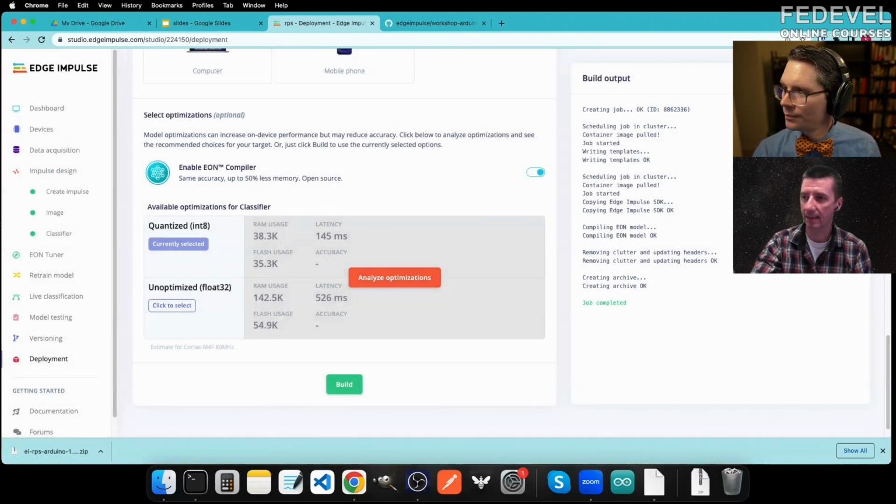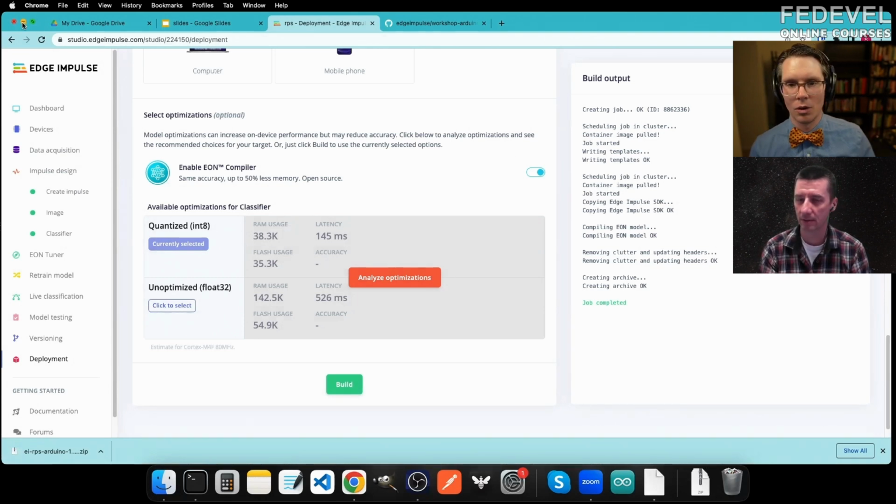So basically, we created some kind of library which is specific for our microcontroller. Correct. All it does is take that model, which is just stored in TensorFlow, all those weights and biases and how they're connected, and then wrap it up into a C++ library. Edge Impulse is nice because it takes that and makes an Arduino library over it. I believe TensorFlow Lite Micro has some Arduino options for it, but this is just much easier to use, and you can watch me push buttons rather than go through hundreds of lines of code. So it's just wrapping that whole thing up in an Arduino library, and we're just going to import that. And then all we have to do is feed it data, and it spits answers out for us. Okay. So now we've got this funnel, it's a library.